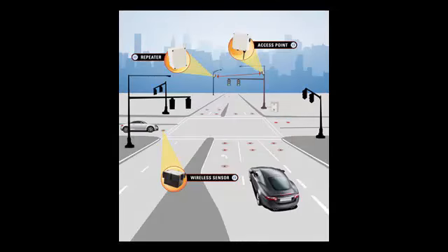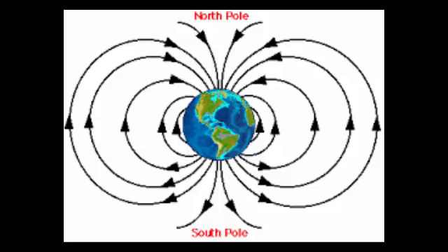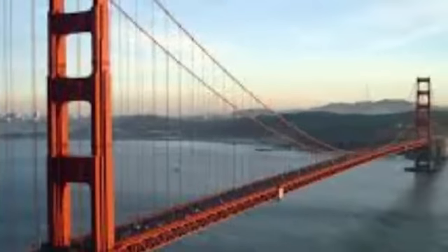Magnetometer measures changes in both the horizontal and vertical component of the Earth's magnetic field. Magnetometers are useful on bridges, decks, and viaducts where the steel support structure interferes with loop detectors, and loops can weaken the existing structure. The magnetometer consists of small in-row probes, a leading cable, and an amplifier.